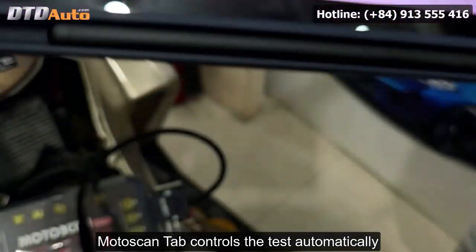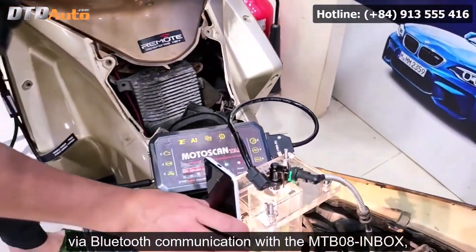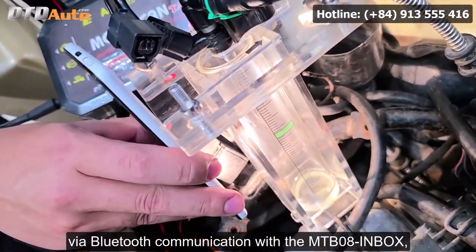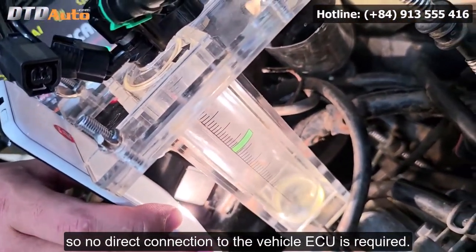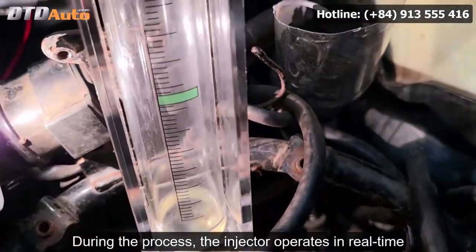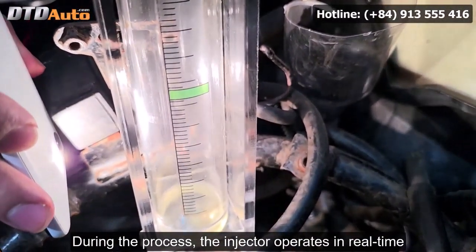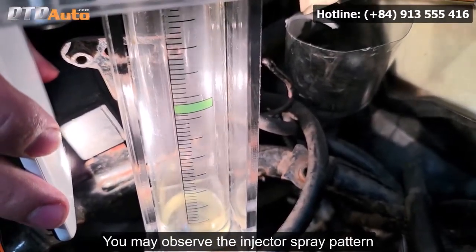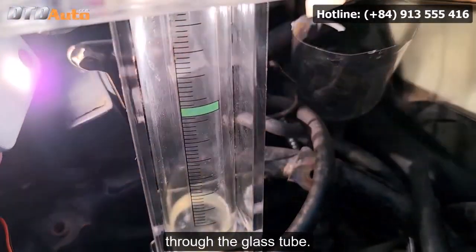MOTOSCAN tab controls the test automatically via Bluetooth communication with the MTB08 inbox, so no direct connection to the vehicle ECU is required. During the process, the injector operates in real time, under controlled pulse conditions. You may observe the injector spray pattern through the glass tube.